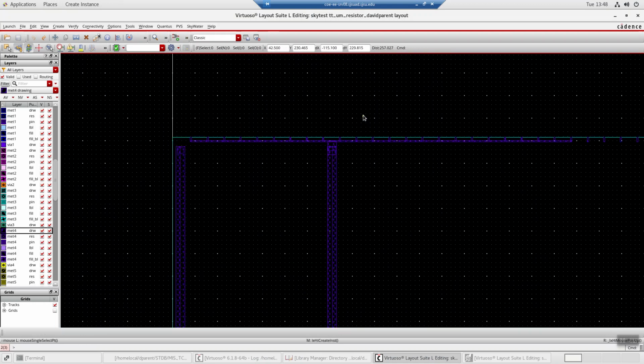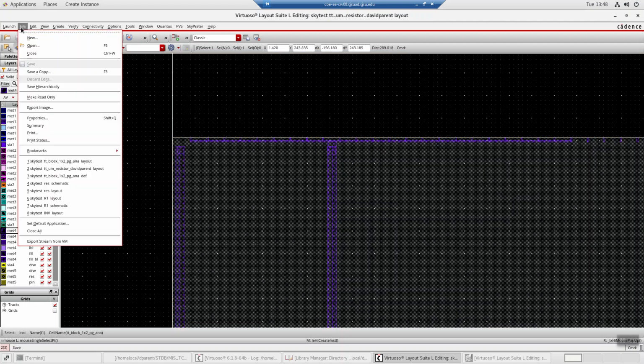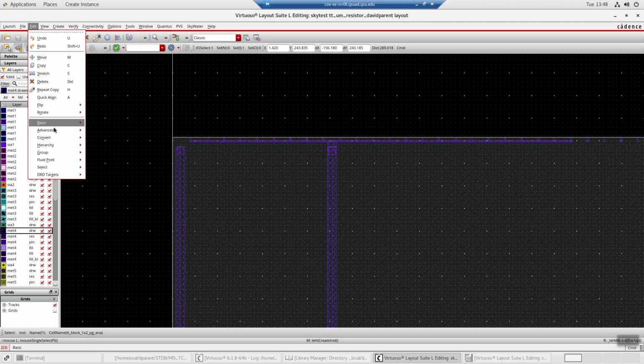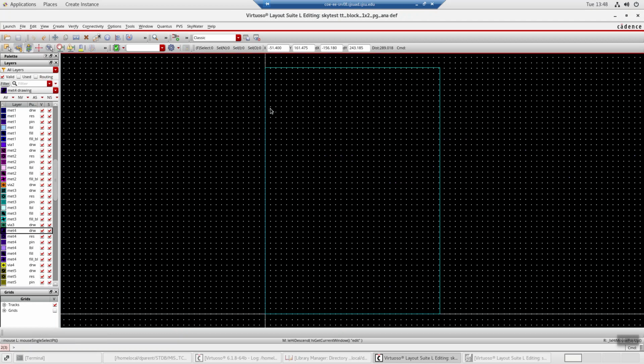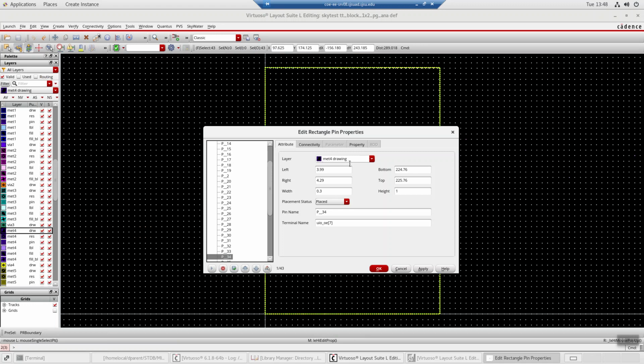All right, so fortunately for me, it looks like it loaded in a def file, because you don't see a rectangle there. If I just send edit into this, and again, sorry, this is a very rough video, if I just select it, highlight, and press Q, all those things are still there.